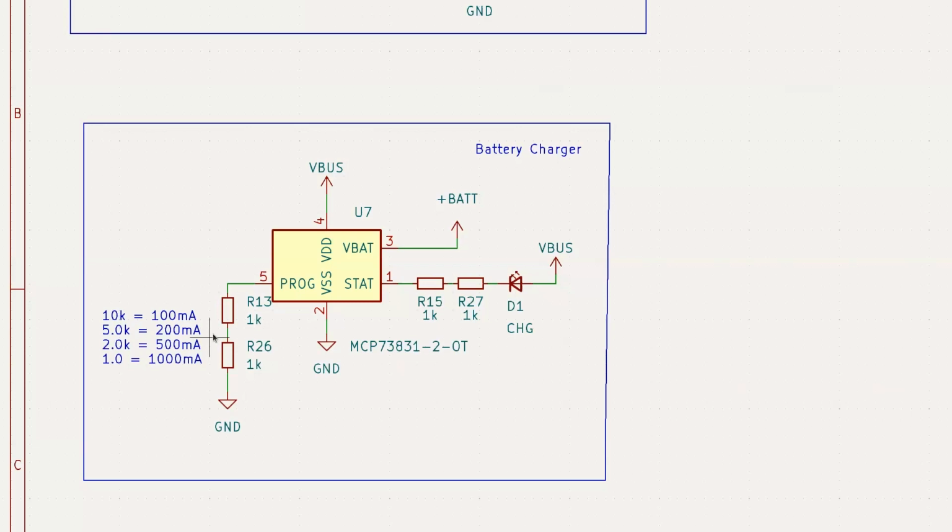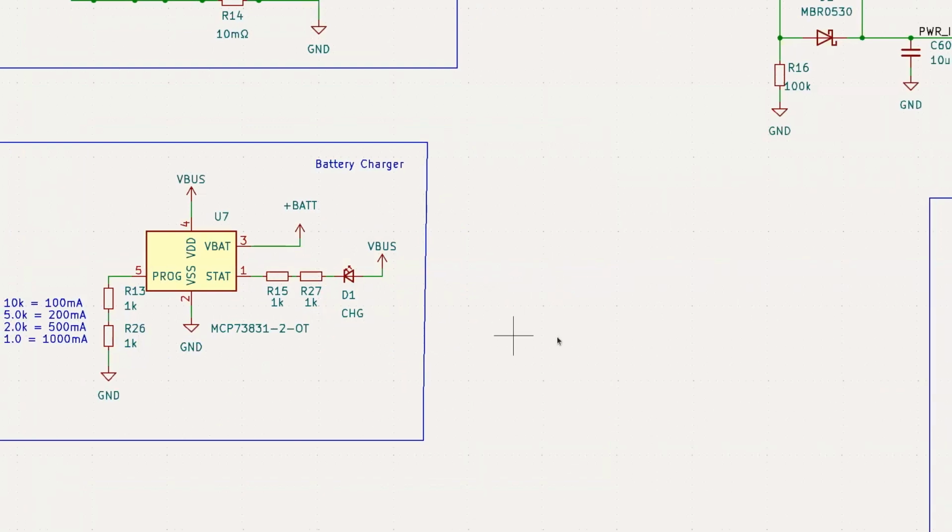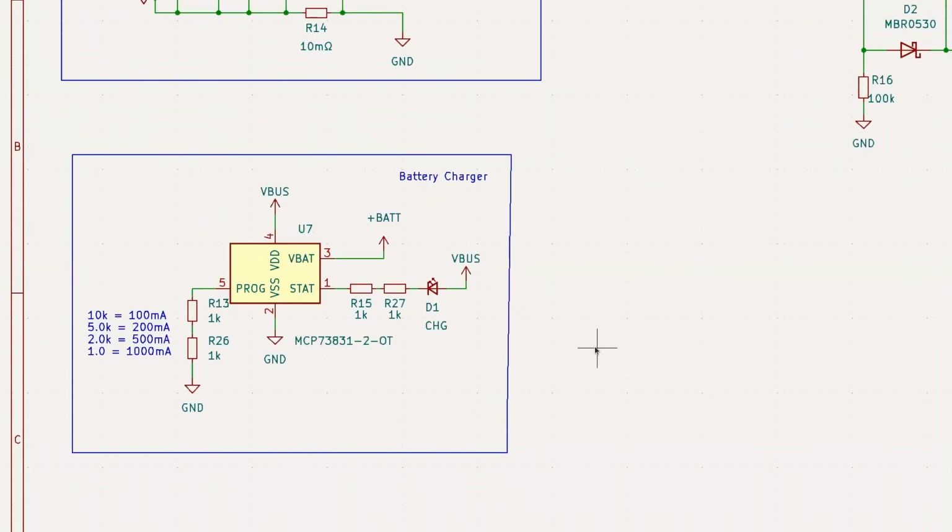Does it do the minimum? I don't think it does that part. So we don't have, what's the other type of protection so you don't completely kill your battery? Under-discharge, under-voltage protection. We don't have that on this thing. Which is critical. It's something that we have to pull into the design. Yeah, you need a charge controller.